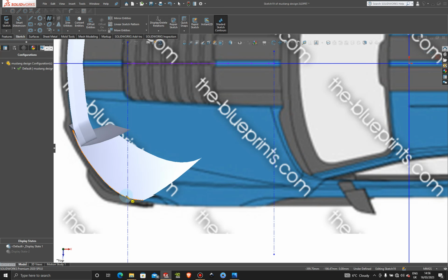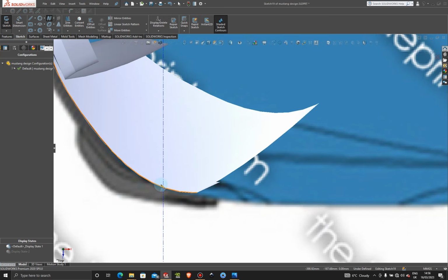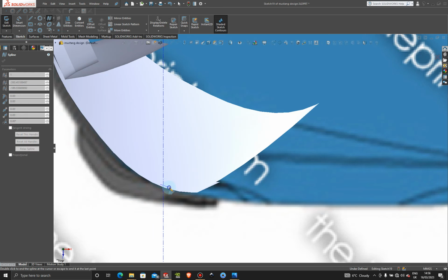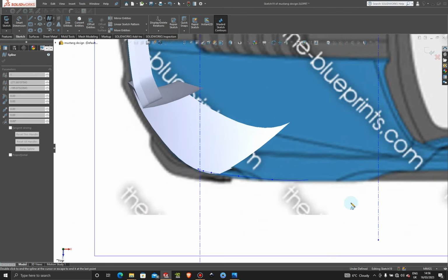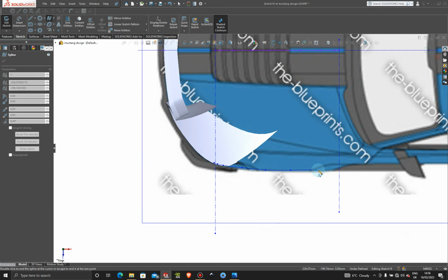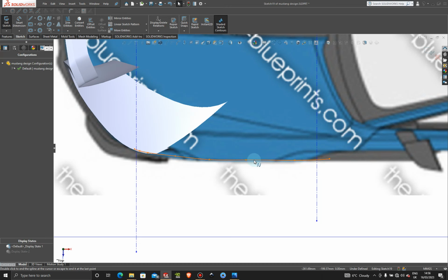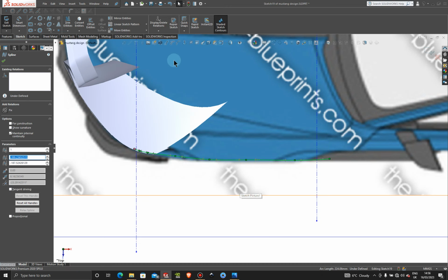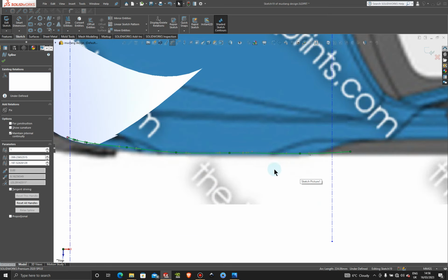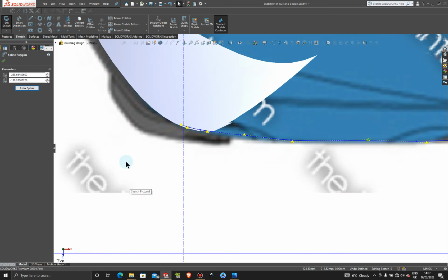Okay, starts from right over here. I'm gonna go up past a bit. I'm just gonna follow this edge. I'm gonna go up past here as well, just like here. And now once I have this, oh yes, this is not straight, so I'm gonna drop our control polygon on there. I'm gonna click on those points and then make this curvature nice and straight.